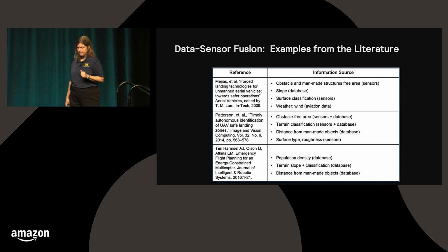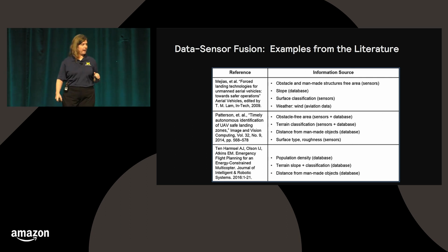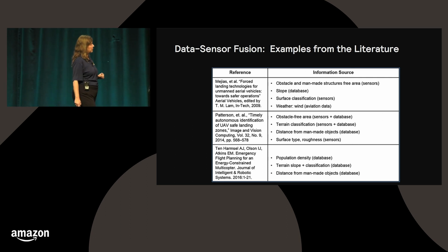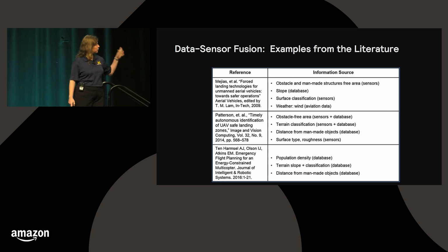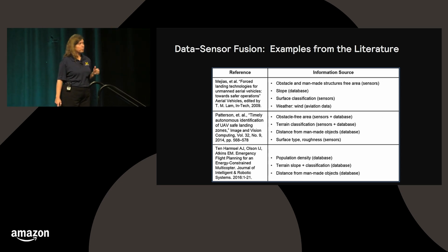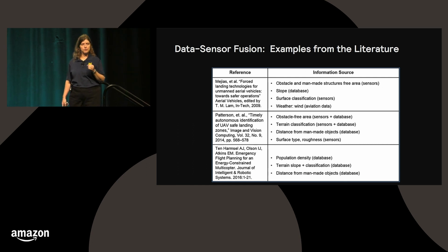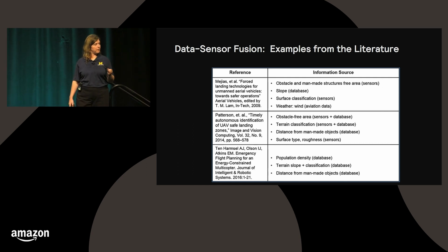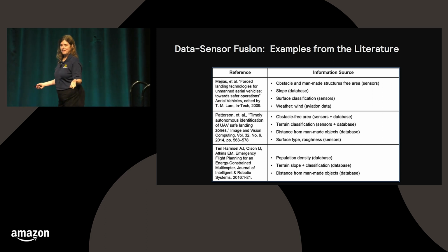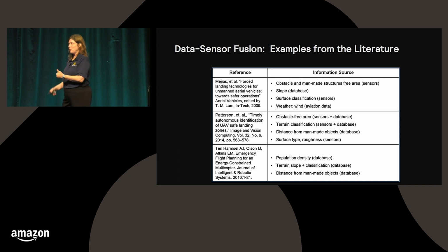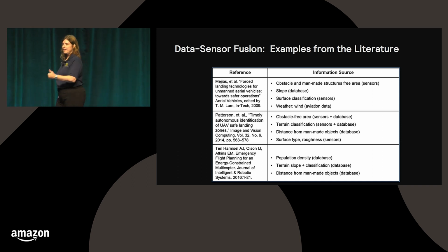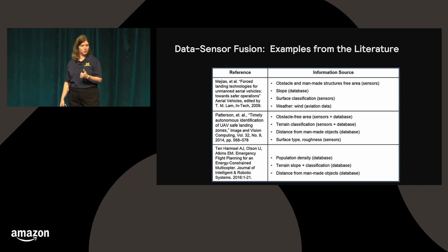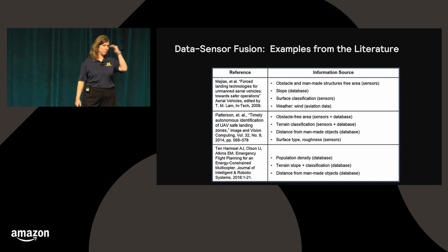You also want to have other information that gives you more about the risk to people and property. Right? As we move from manned to unmanned aviation, the risk shifts from save the airplane and save the people on board to who cares about the airplane? Now, maybe we care, but it's less important to save the airplane than it is to make sure that that airplane never brings damage or harm to people on the ground or expensive property on the ground, with the people ranked highest.